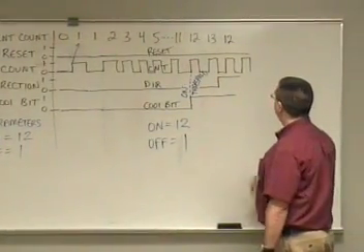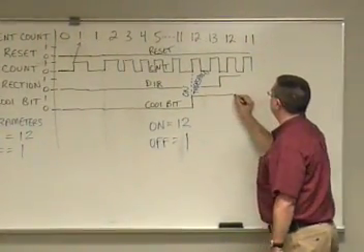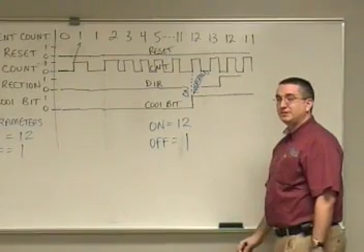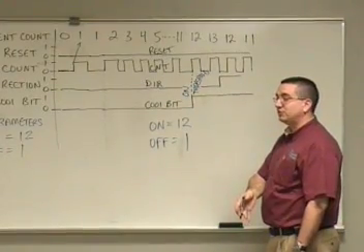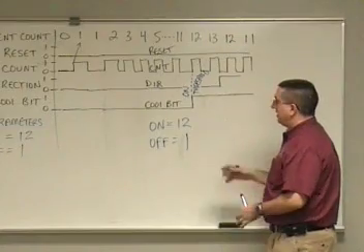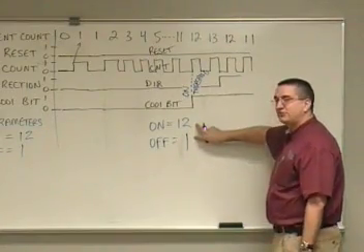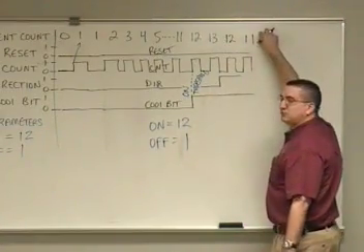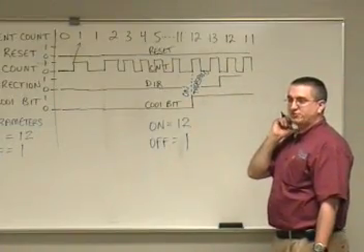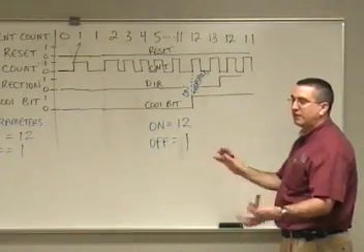It's down to 11, but the C001 bit is still on, right? Yep, because I'm not less than the off threshold. So that's one kind of strange thing. If these were set equal, if it was 12 and 12, as soon as I got to 11, the C001 bit would have de-energized. And there may be times that that's what you want to happen.